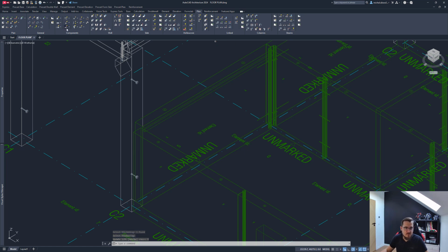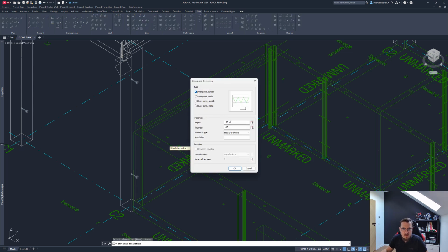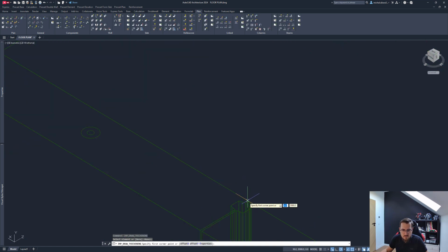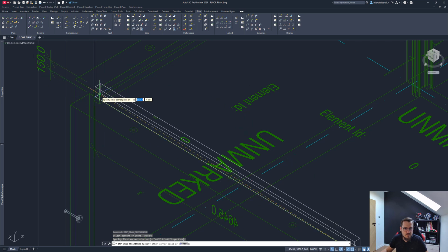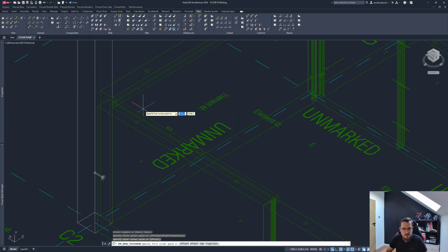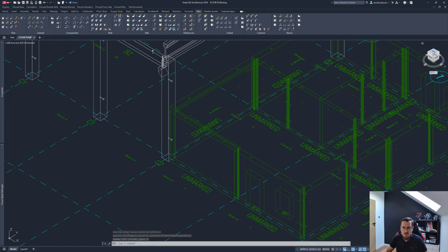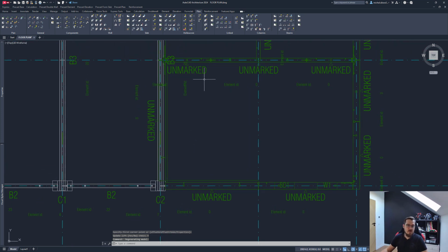Let's maybe add panel thickening as well for this wall, just so we're consistent, right? And it's going to be the same thing. And let's accept that. Okay, and let's do that from this point. Right, and you can see the preview. Maybe working in 3D is slightly better for this. All right, let's snap that to the bottom, and like that, we have a panel thickening. Let's accept that, update lifts, and now we have panel thickenings, which is perfect, because now with panel thickenings, I'll show you later how to add reinforcement to that on the drawing, but now let's actually place some slabs for us.